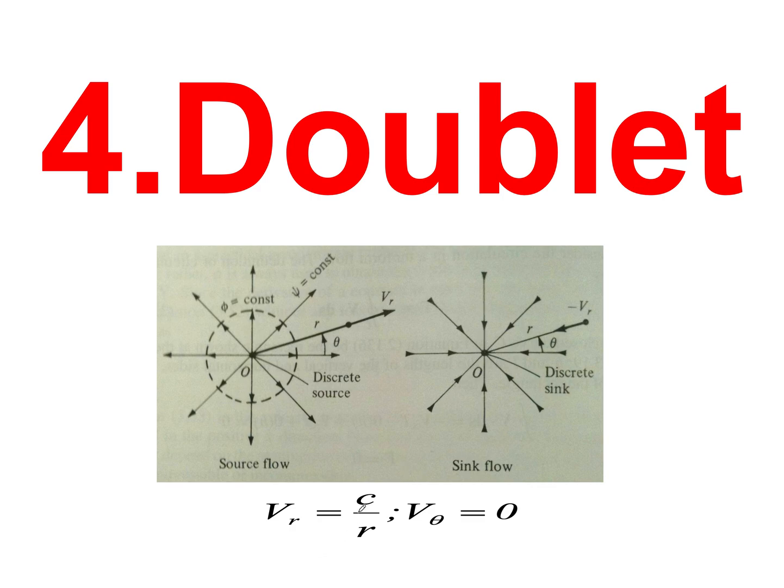But when you put in r equal to 0, when you sum up the source and a sink, you're summing infinity minus infinity, and infinity minus infinity does not actually equal 0. It doesn't necessarily have to be equal to 0. It can, but not necessarily. So we need to use something like limits. We need to find the limit when r is equal to 0. What do the streamlines look like? Because we found that outside r equal to 0, sure, the radial velocities will identically cancel out.